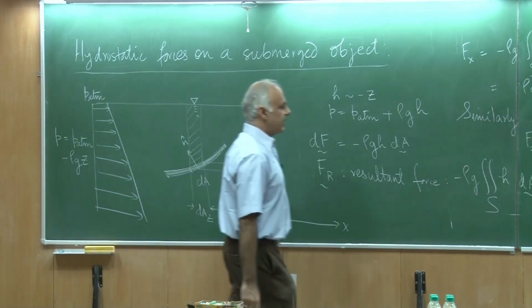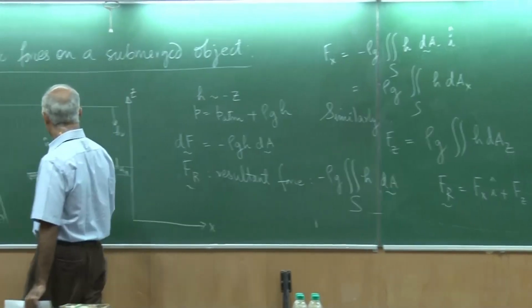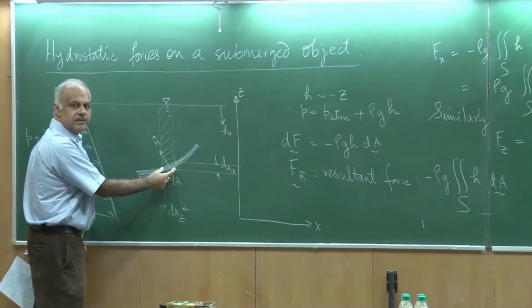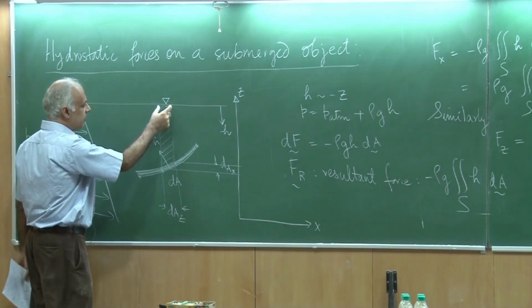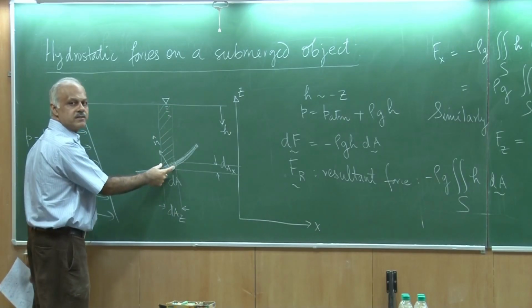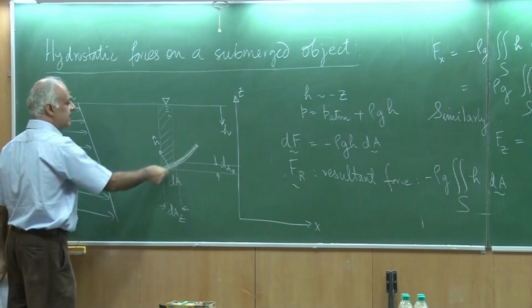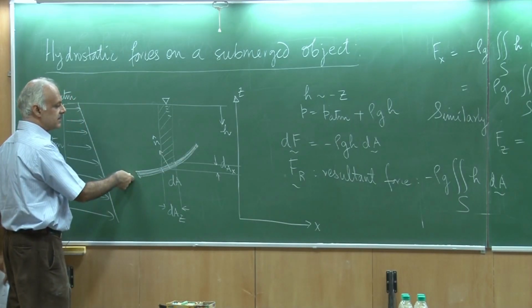So, if I want to calculate the force in the vertical direction, I take a small element and calculate what is the force exerted by this prism of water, and simply integrate it over the entire length of this object.